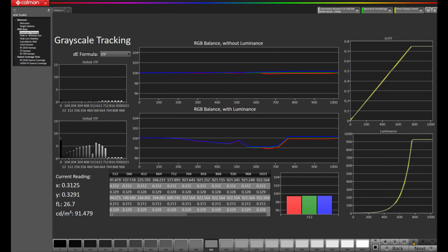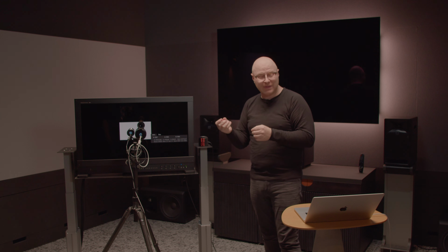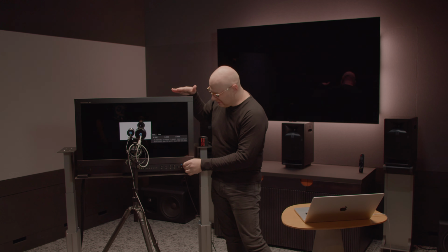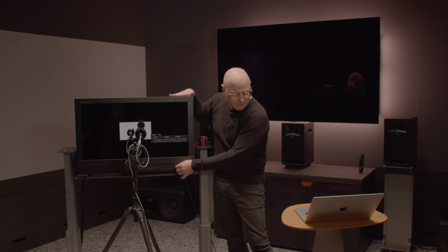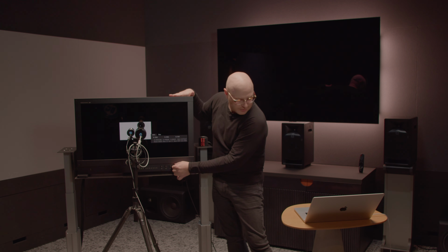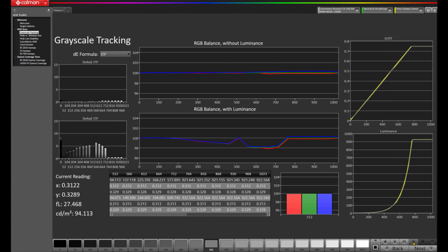The amount that's over 200 nits is a lower percentage. Over 400 nits is a lower percentage. The amount of content that's actually at 1,000 nits or 4,000 nits is going to be less than 1% of the pixels on screen during any movie. So we don't really want to target that very small amount of the pixels that we're seeing. So I'm going to adjust this and bring up that EOTF curve to try and track PQ better.